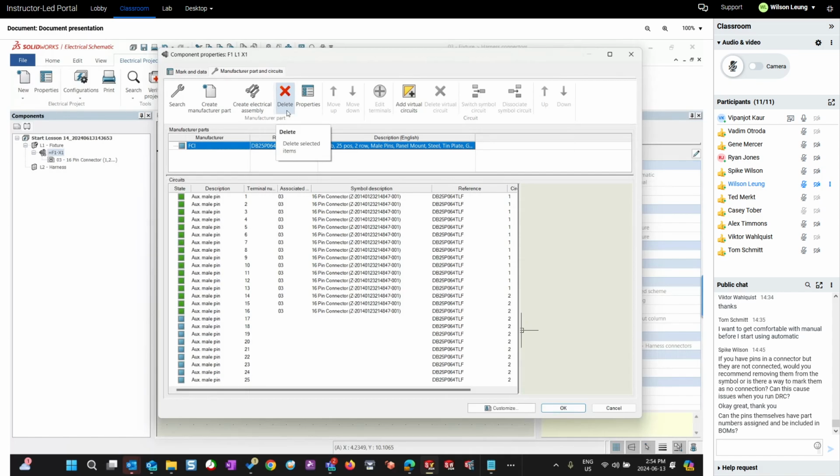right? So I cannot show, it doesn't make sense. Think about it. If I'm buying a cup, right? And there's tea in the cup, I cannot show the tea as my BOM item, right? So why would you want the property of it? The actual thing is going to show in your BOM, not the properties of it, not the pins of it, not the subcomponents for it. Spike, does that make sense? So you cannot show the pins in the BOM.